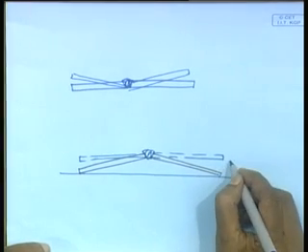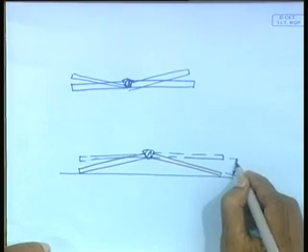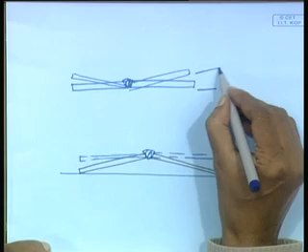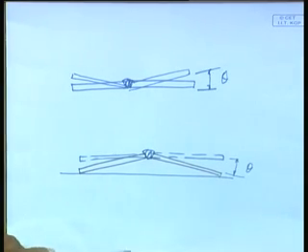So, what I have to know is the angle of presetting, or in other words, how much it may deform. If I know how much it will deform, so much pre-deformation I give, I align it in that fashion, so that when the welding is done, the same principle of shrinkage forces and bending moment will work. So, it will bend and come to the straight position, right. That is what is called presetting.